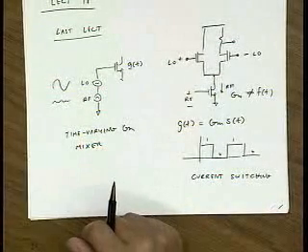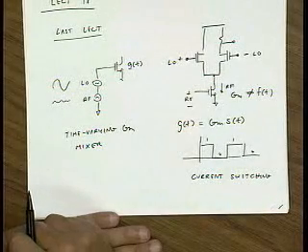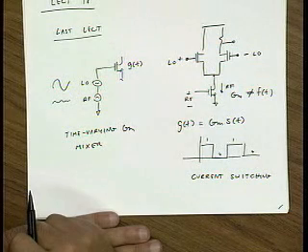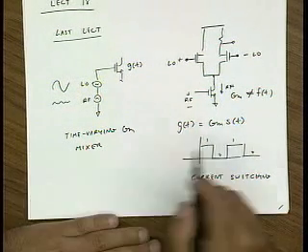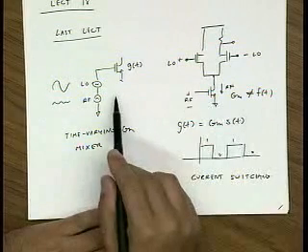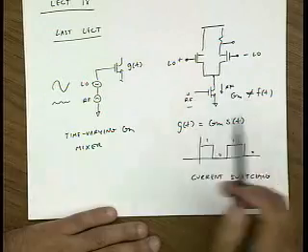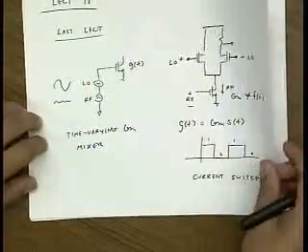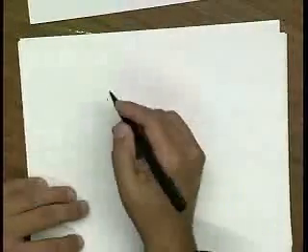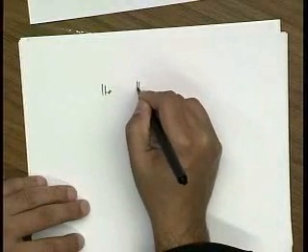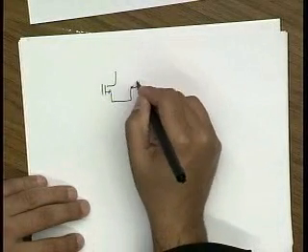Yeah, on the right side of the diagram, can you change the position of RF with LO? To the bottom tail? You can do that. Large signal at the bottom? Yeah. In which case, it won't be this kind of mixer, it'll be this class of mixer, right? Because then we're varying the bias current, which varies the GM. So let me just draw that circuit. Someone asked a similar question in office hours today. Is this a mixer?